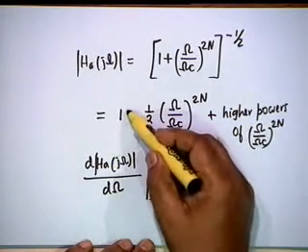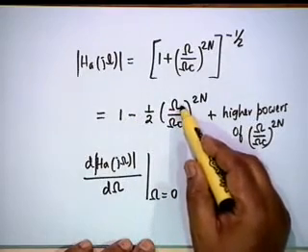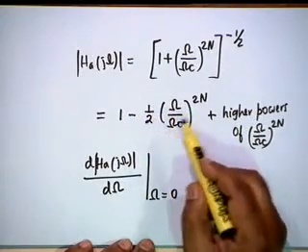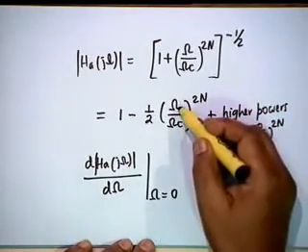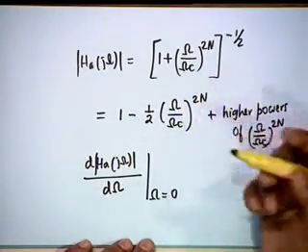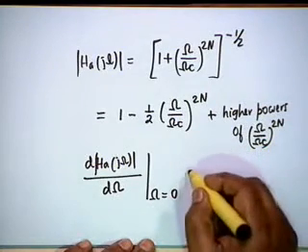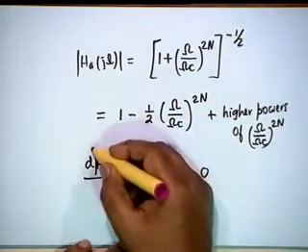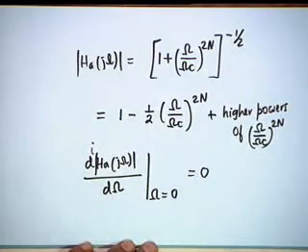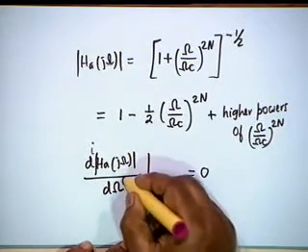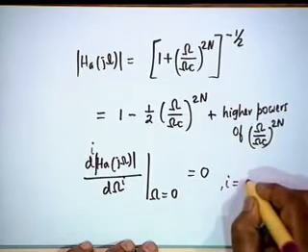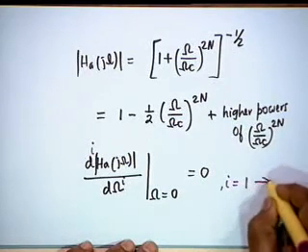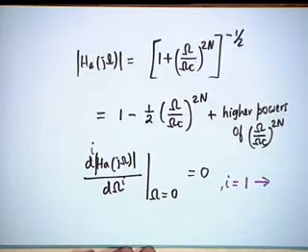omega and put omega equal to 0. If you differentiate, differentiation of 1 is 0. So, you shall get omega by omega c to the power 2n multiplied by omega to the power 2n minus 1, and if you put omega equal to 0, obviously this will be equal to 0. The next differential coefficient shall also be equal to 0, and this will continue up to the ith differential coefficient, where i goes from 1 to how many such differential coefficients shall vanish at the origin?